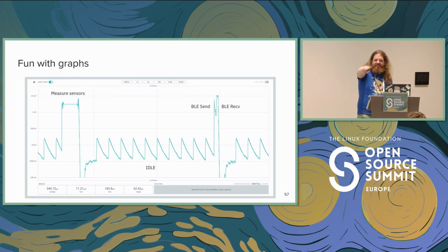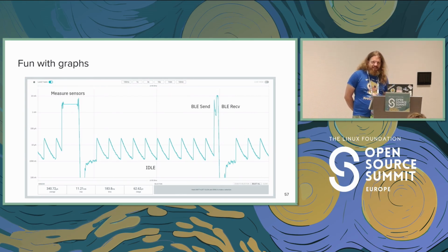There was another question there. Did you consider the internal resistance of the coin cell versus the power consumption needed for TX and RX, in terms of voltage peaks and the brownout, especially when the coin cell drains? Like I said in the first slide, I'm ignoring that the coin cell has any internal resistance, because I didn't do the measurement with coin cells in there.